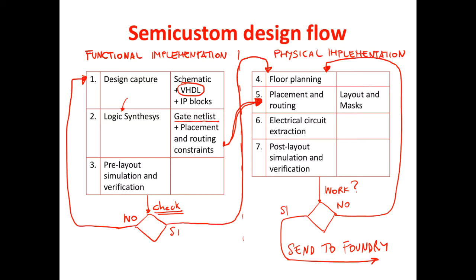We more or less have an idea of the total space that is required by the chip. So the main reason for doing the floor planning is understanding the total space. The exact position of the pieces is, let's say, at this stage less important because we need to adjust it in any case.